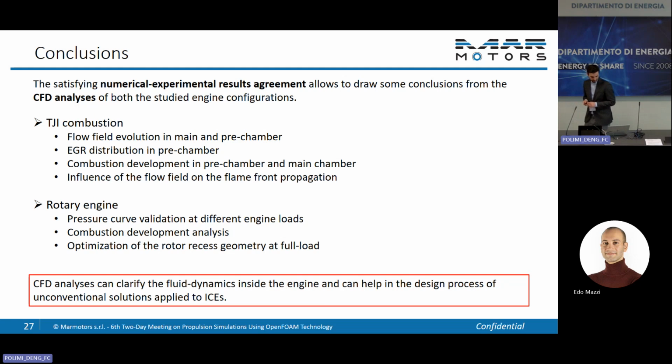So finally, coming to the conclusions, due to good numerical and experimental results agreement, we draw some information from the validation of the model that was done through OpenFOAM, and especially coming to the TGI combustion, we had the possibility to see the flow field evolution inside the main and the pre-chamber, but most of all, the fact that, obviously, it is impossible to see in real life, that we had an asymmetric development of the combustion inside the pre-chamber and then also outside it due to asymmetric jet ejections.